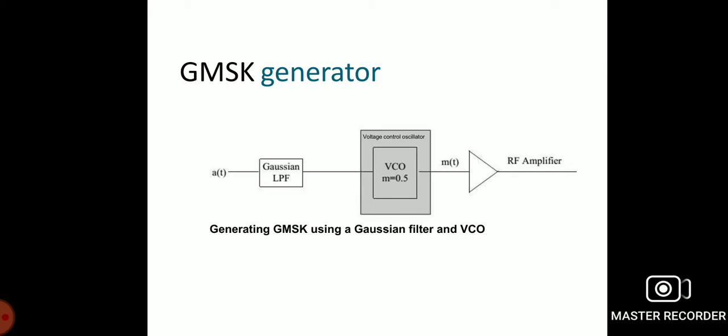Now we can compare the cellular digital packet data system. The system has better inter-symbol interference tolerance. So both cellular techniques, CDPD and the Mobitex system, employ the forward error correction technique in the packet transmissions. So GMSK offers a straightforward, spectrally efficient modulation for wireless data transmission systems, and also the